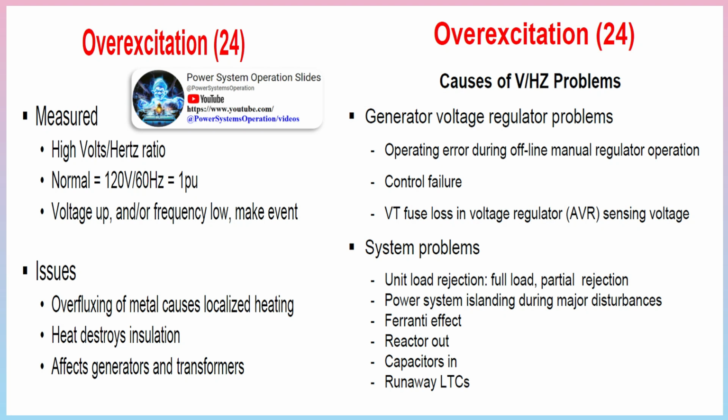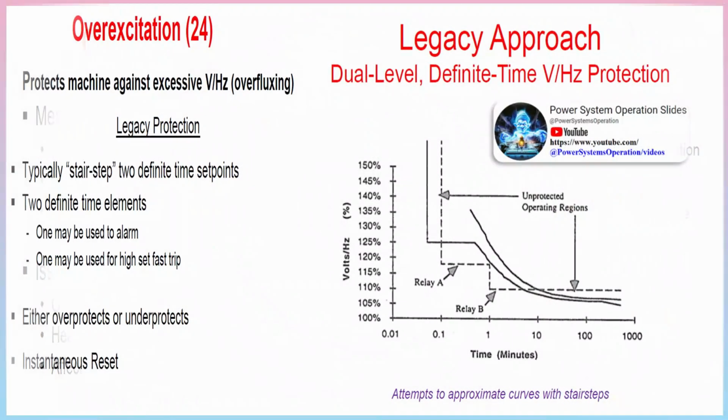A negative sequence digital relay protects the generator down to its continuous negative sequence current I2 rating, versus electromechanical relays that don't detect levels less than 60%. Fault backup is provided, and it can detect load unbalances and open conductor conditions.